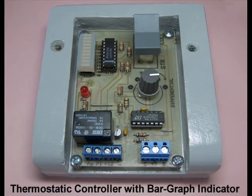If we set the differential too high, we'll collect less heat. But if we set the differential too low, the power consumed by the pump may be greater than the heat collected. A counterclockwise setting maximizes the heat harvest, and a clockwise setting maximizes the energy conservation.